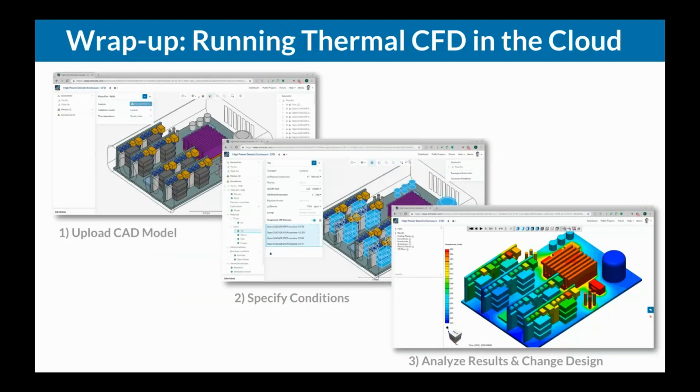And with only 8 minutes in overtime, let's wrap this up. I think what we've seen over the last 25 minutes is how we brought in a typical enclosure from my local CAD system, brought it into SimScale. This is what we've seen in the top left, right? What we've done is we created a flow volume extraction.